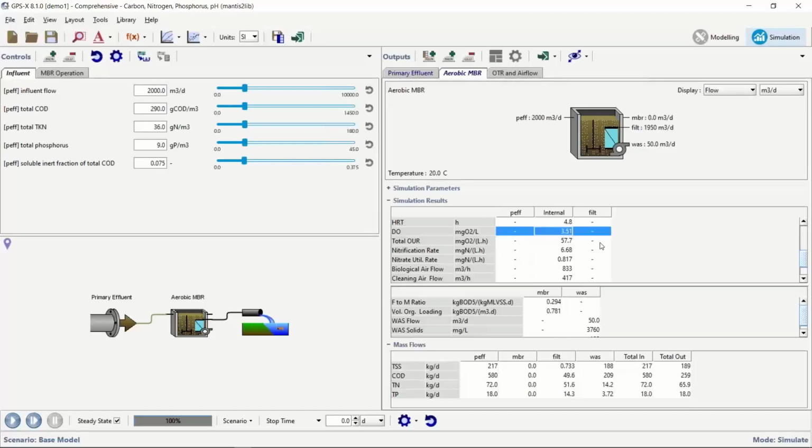If we turn the DO controller on and give it a DO set point of 2 or 3 or whatever number we like, it may behave a little differently than you expect, because it's already got this other secondary aeration source that might be providing some of the effort it needs. So it's an interesting aspect of how these systems work when you've got this dual aeration system happening in the same tank. Okay, I think that shows you a little bit of the details.